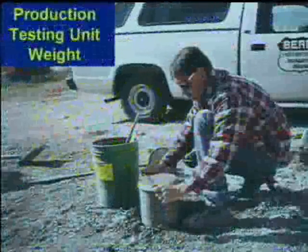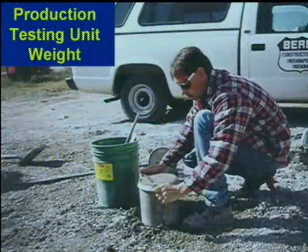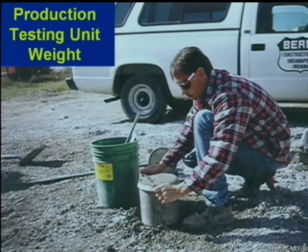Unit weight testing, as we mentioned before, figuring out what a unit weight of concrete is can help you out tremendously with keeping track of your aggregates, keeping track of your air inside of your mixture. So by taking unit weight, the basic idea here, and this is an air test before the air test is done, dump the concrete in here, you can figure out the weight of this bucket full of concrete. You know what the weight of this bucket is when it's full of water. You can basically figure out what the density of this concrete is, what the weight of this concrete is per cubic yard, per cubic foot, and see if it matches up with what you expect from a theoretical calculation.